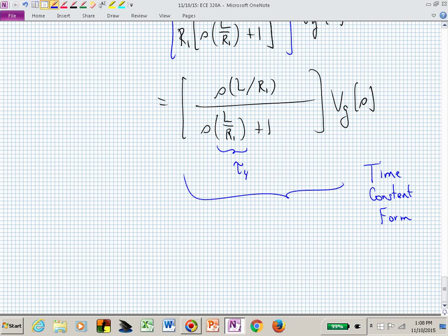Question? No. So the question, that's a good question. Does the S in the numerator have to be multiplied by the same tau? No, it doesn't. We are just looking for time constants in our denominator expression, and in this case it's easier because it's first order.